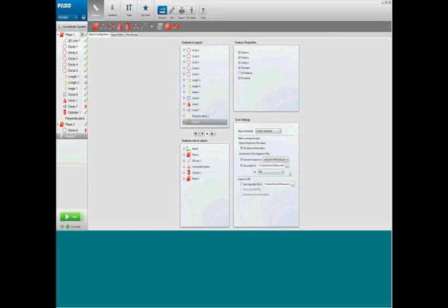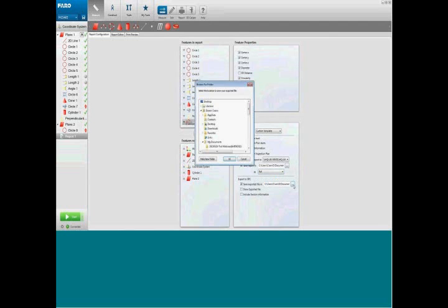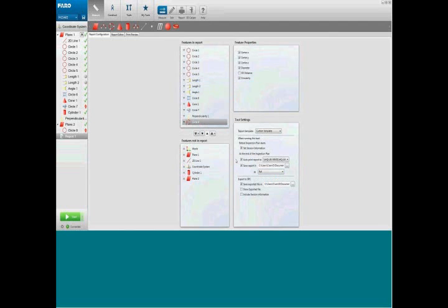Where the data is to be used for SPC software, we can export a CSV version by clicking here and choosing the location. To activate the report, to create the automatic save features, from the feature tree on the left, we right-click and we click Start Report.